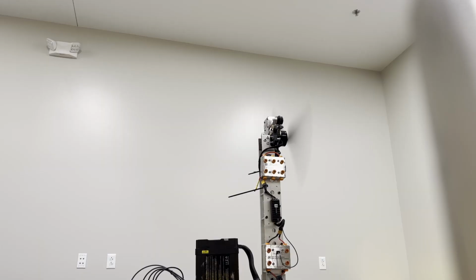For propulsion, we're using 20-inch carbon fiber propellers that have specially constructed tips that will reduce the vortex and increase the stability of our drone. We're using agricultural drone motors that have a kV ratio of 340, and they're 3-phase power motors.